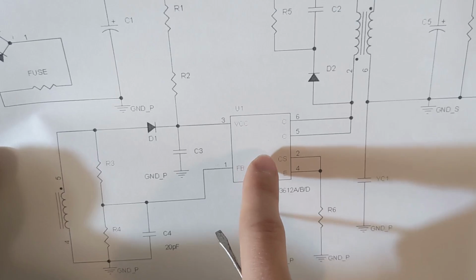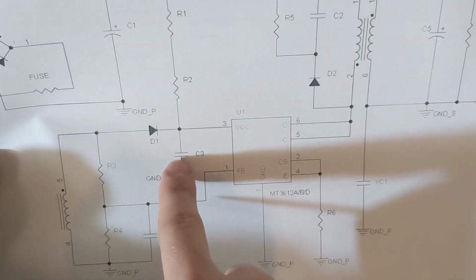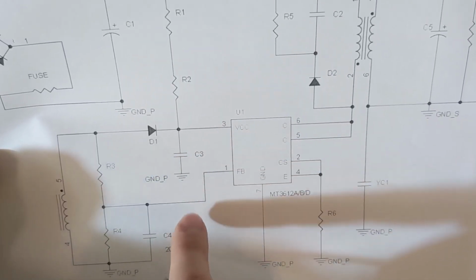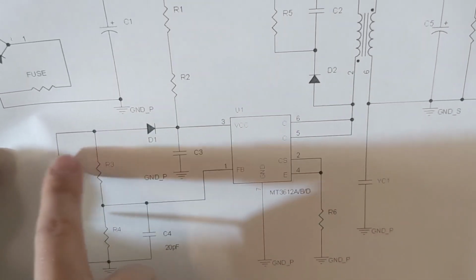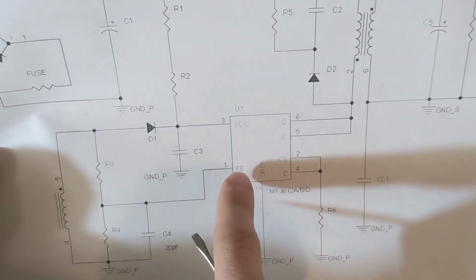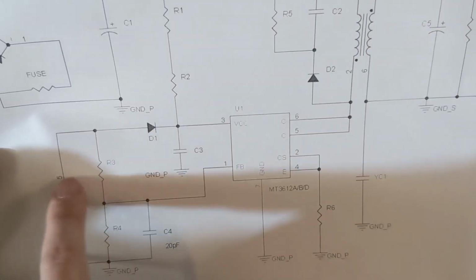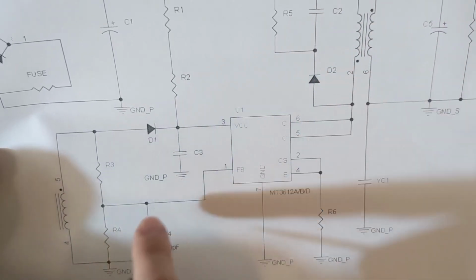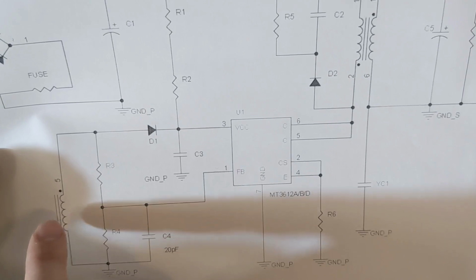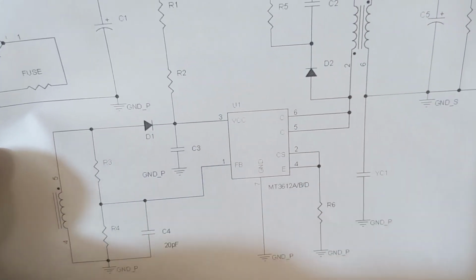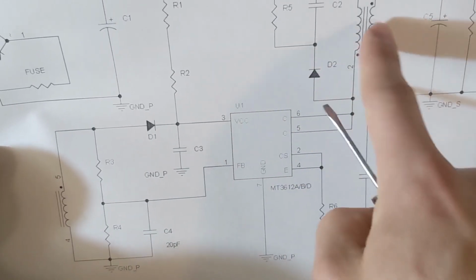But once it starts switching on and off, then it looks like V1 would provide rectified power with C3 as a filter. So this is kind of just a generic thing, and then you also got feedback here. Based on this resistor divider and the voltages here, you will get feedback on this chip, based on what's happening in this transformer, which is the same as this one. They're just showing it differently here. It's one big transformer. So this winding basically will know what's happening in here and feed it back. That's how this chip knows how much duty cycle to be switching this transformer.